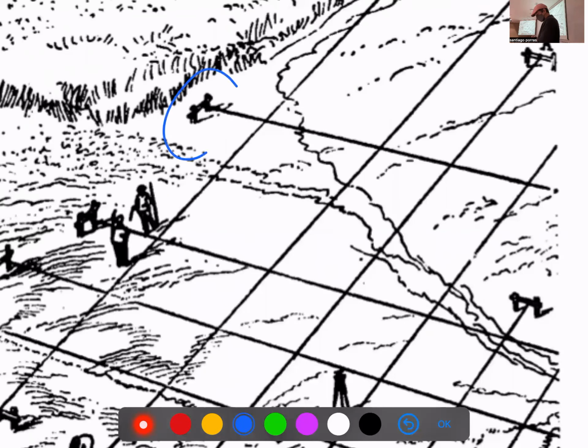This is one detail of those elements, right? And this we still do today like that. Sometimes we can use laser to have more precise measurements, but then those strings, like 3-4 millimeters thick, I have to put them by hand. So it is totally unrealistic to think the 1 millimeter precision will happen on the construction site.